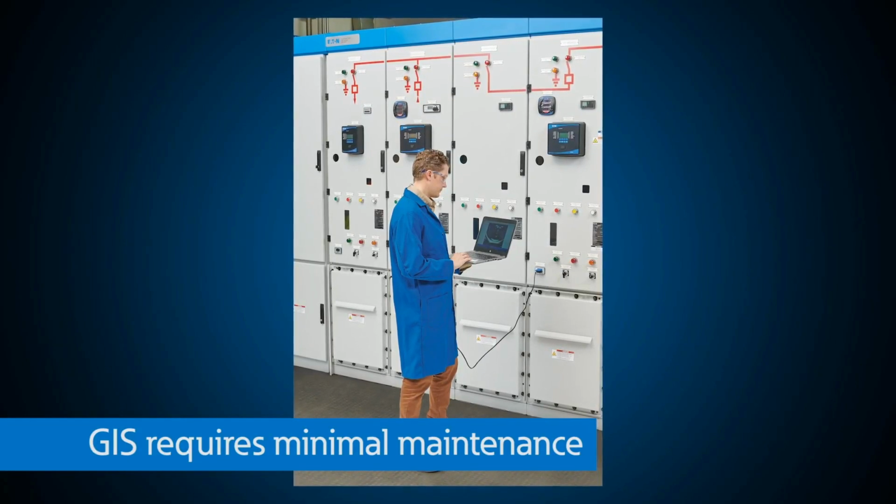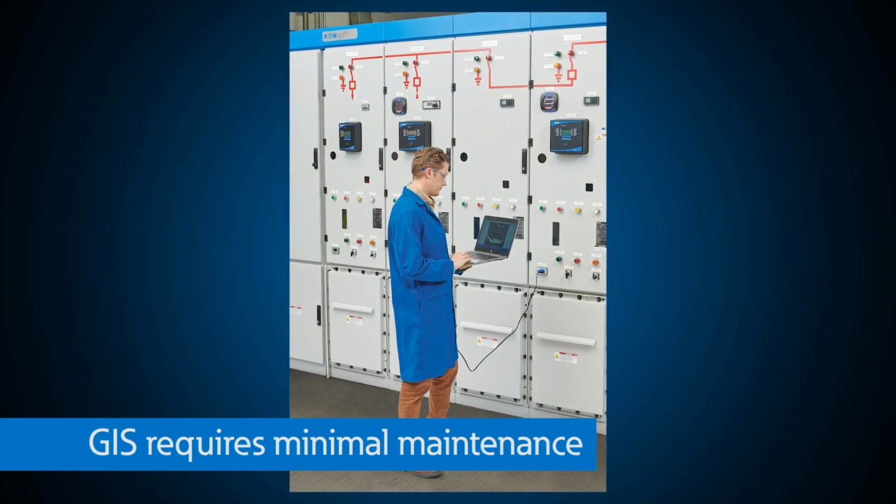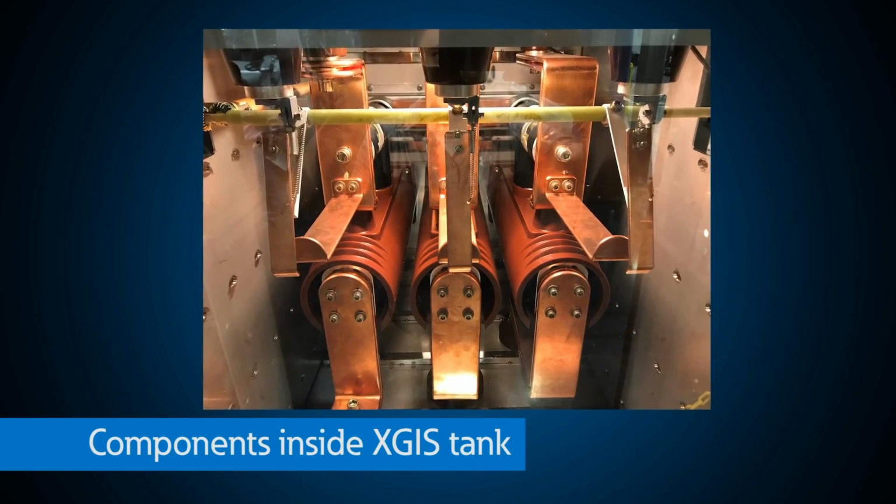Equipment, AIS or GIS, must be selected based on the equipment's ratings and capabilities to satisfy actual application requirements. GIS equipment offers a smaller footprint and space savings, but may have a high initial cost depending on the voltage class. However, GIS requires minimal maintenance compared to more regularly scheduled maintenance activities for AIS due to the vacuum interrupters being contained in SF6 or an alternative gas where they are not exposed to particulates and the environment, as they are for AIS. When future changes are expected in the lineup, including things like increasing a breaker size and adding auxiliary compartments and retrofitting to integral racking, AIS should be considered as it provides operational flexibility for modifications to the equipment cells.